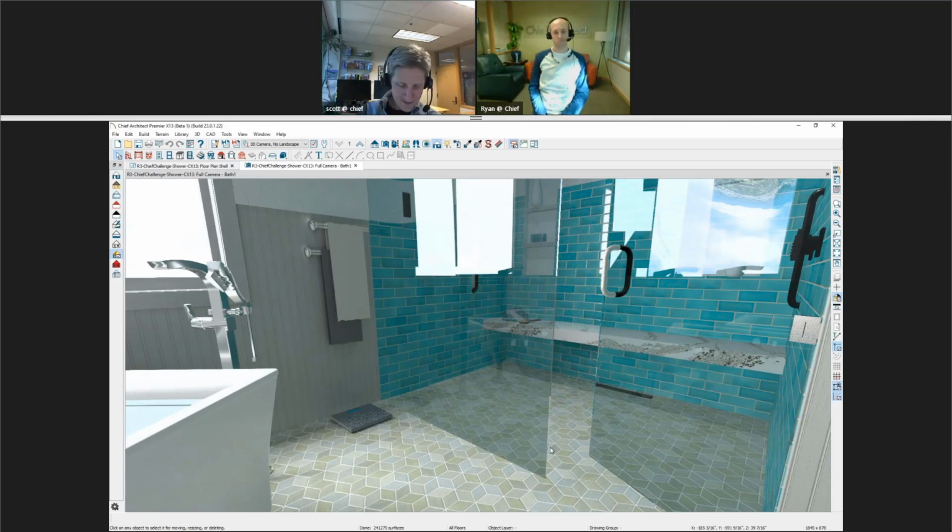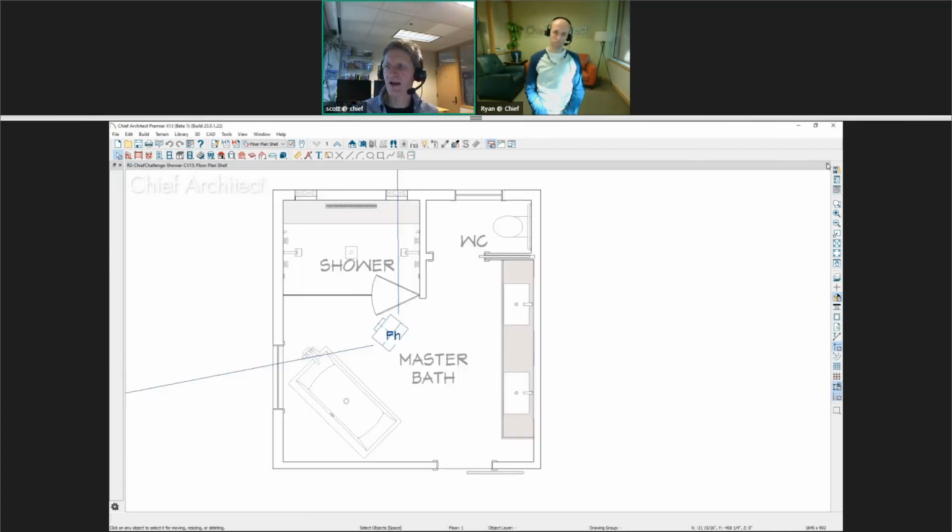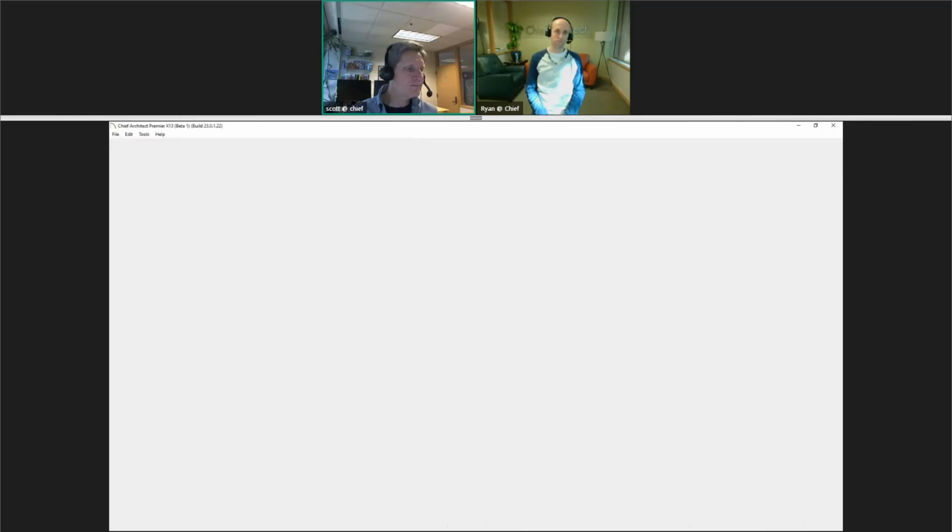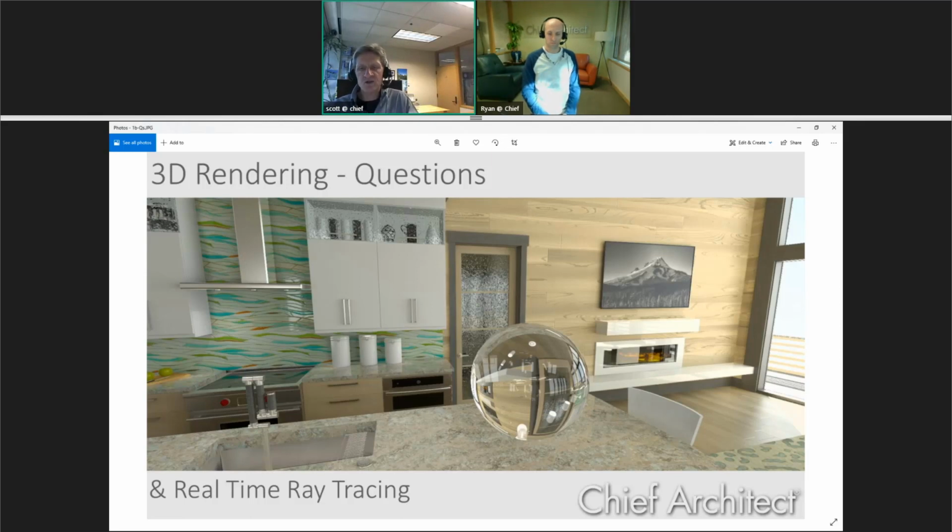Okay, and then I've had a similar issue with invisible walls where it's just a room divider. You have a doorway with no casing on it. This invisible wall cuts through the drywall, and I have had trouble getting that outside corner to show properly. Yeah, sometimes maybe when it meets exactly a certain corner right at the end, I'm not sure I have a plan open that shows that exactly, but you can get into a situation that it cuts that. But again, make sure your wall is marked as a partition wall. I would start with making sure that you've got your wall set up as a partition wall to eliminate cutting through the different layers.